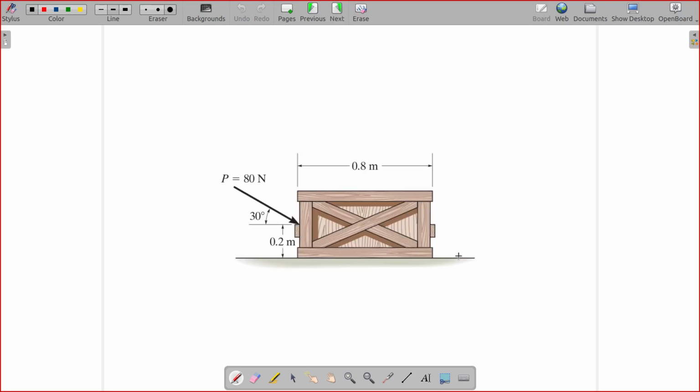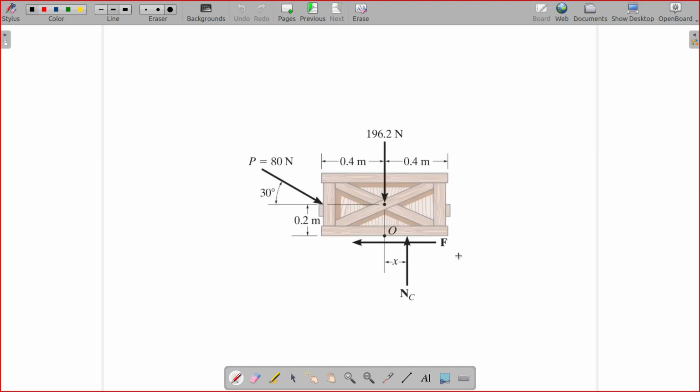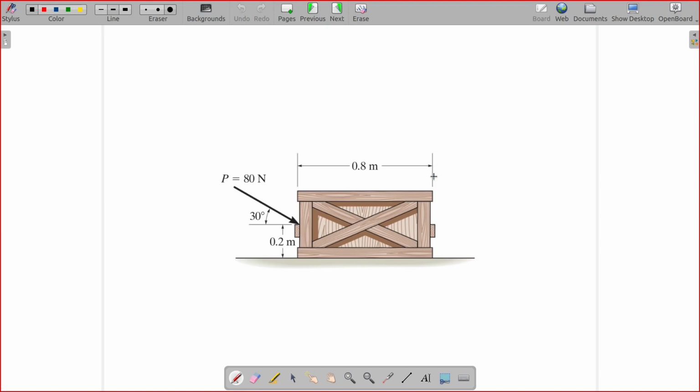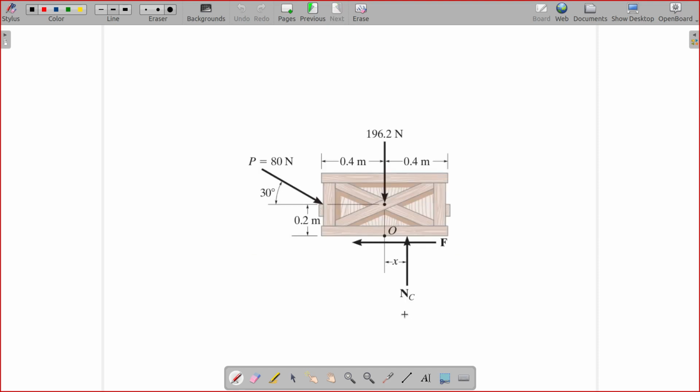You simply write down all external forces. P is given. We know the weight of the object, so mass multiplied by g will be the external force downwards, and you will have a normal force from the surface on the object, that is N. F is the frictional force, which will be in the opposite direction of the external force, and in the tangential direction of the surface.